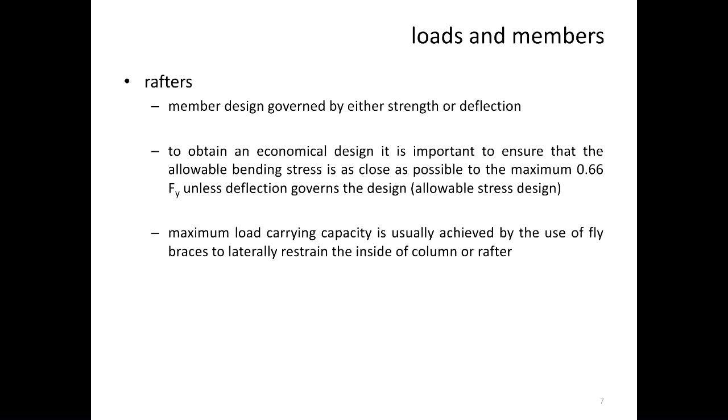We factor that down. What that means is if the yield stress is 300, we factor that, say, by 0.8, so we only load it up to 250. Despite the yield stress being this much, we only load it up to this much. And then you've got the yield stress, and beyond that you've got the reserve strength. So you can see that our structures are mostly designed safely around the world. That's what this is saying, looking at allowable stress design, wherein the possible maximum stress is taken as 0.66 times the yield stress. So you don't go beyond that normally for these structures.